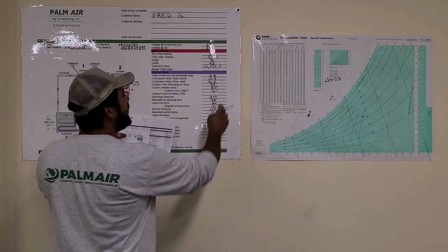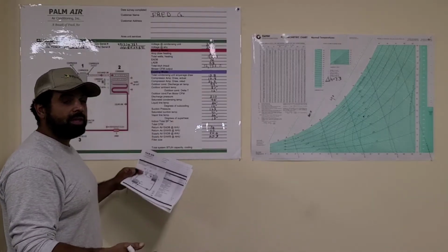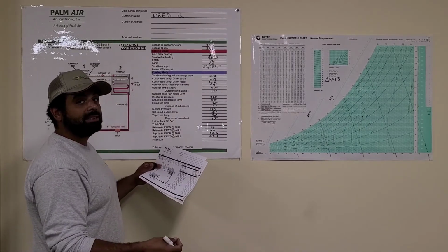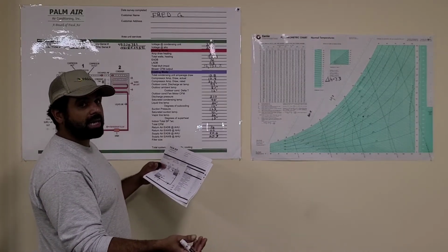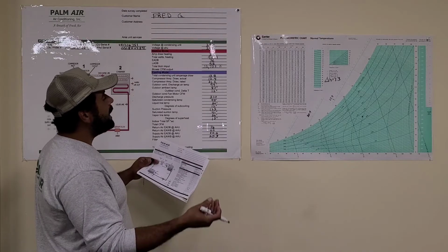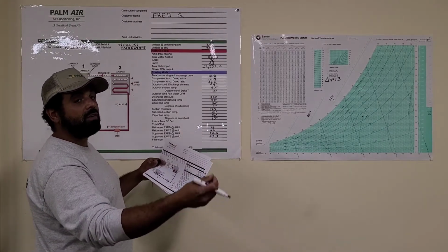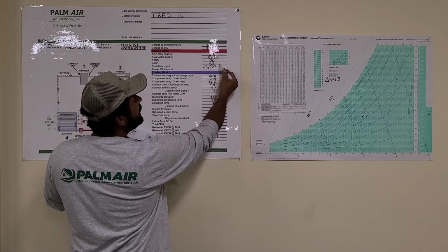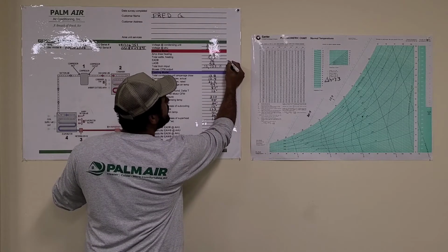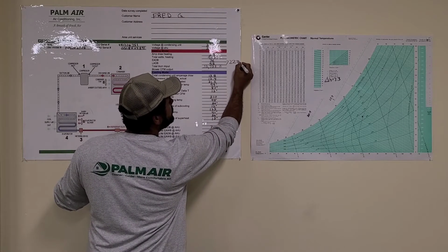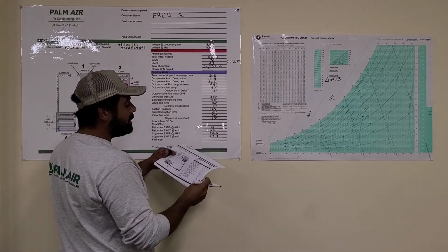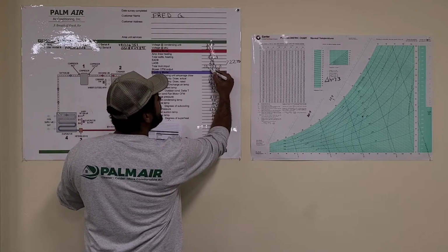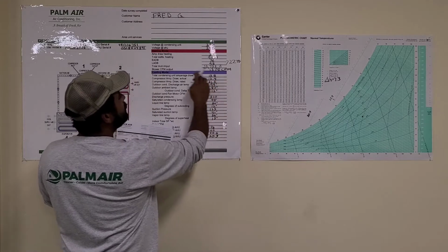And once again, we're now going to do our heat rise method. We're going to take our 32,752.2 and divide that by 1.08, because 1.08 is my constant sensible heat factor. Once we've done that, we're going to divide that by my temperature difference, which in this case is 22 degrees, 76 going in, 98 coming out. That leaves me a 22 degree temperature difference. And when we do that, we're going to come out to 1,378. That's CFM. That's how much airflow this is actually moving.